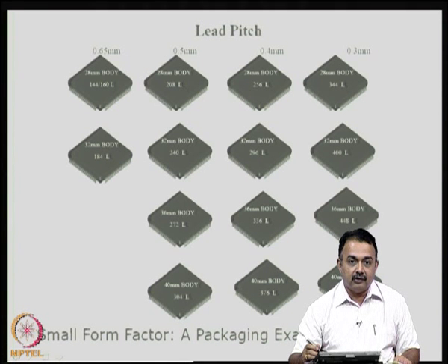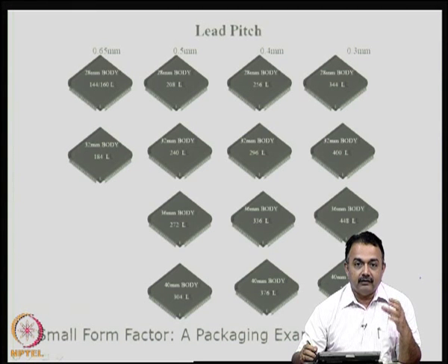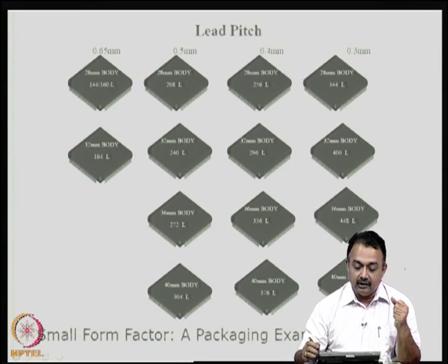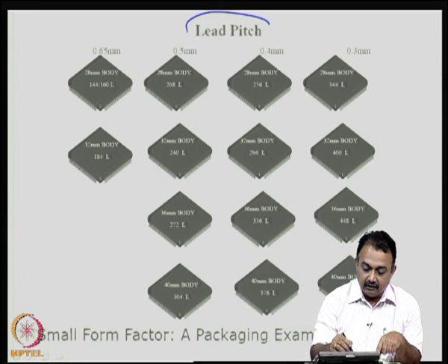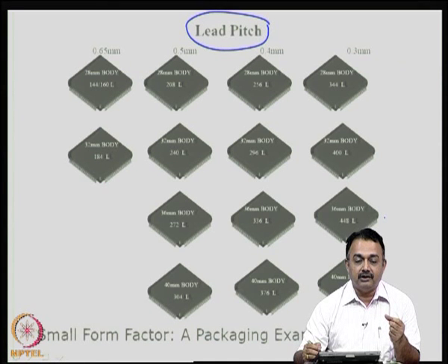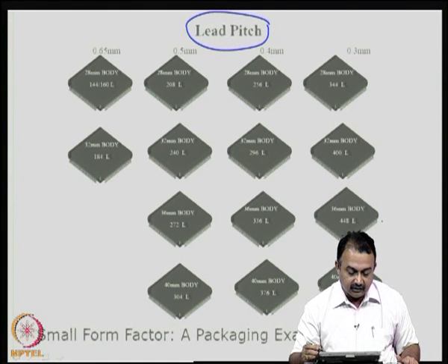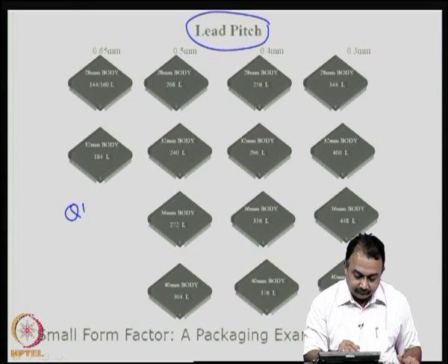Another example I would like to give you to impress upon you about the packaging evolution and sizes, and you should always get a feel about lead pitch. Once you get a feel about the sizes and number of lead pitch, you will be able to appreciate technologies that are being used at the board level. Pitches are also very important at the chip level, because you need to understand what pitches are available at the die level. For example, this is a quad flat pack structure